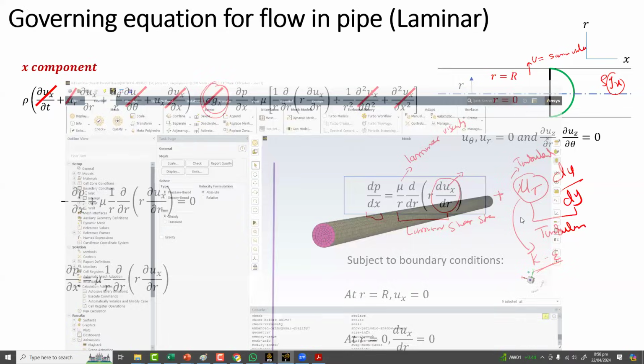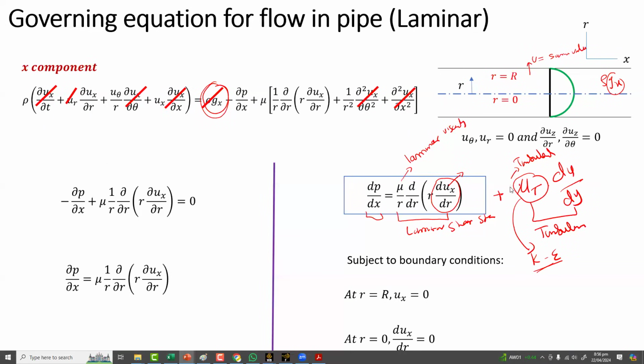Now, if you have the turbulence quantities here, then you go for a turbulence model. The whole problem revolves around finding the turbulence parameter, that is, the turbulent viscosity. This is not a fluid property, this is a flow property. So the question is how to find this value. There are various methods, like Prandtl's mixing theory, and very simple turbulence models, but they require tuning for every flow. Every time you have to put in some parameters to solve that particular problem. So they wanted a universal turbulence model, and then they came up with the k epsilon and k omega types of equations.